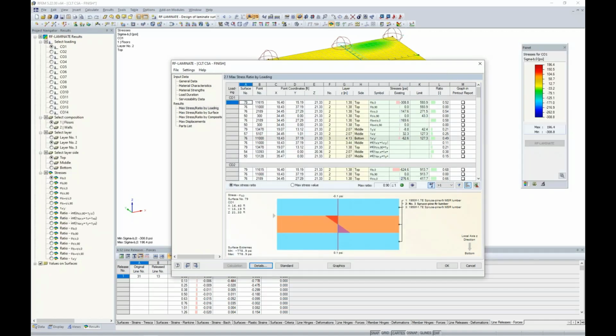So once you've applied the average regions, come in here, check on this checkbox. You can run your calculation again, and now we take a look at our max design ratios, and we see a max check now of 0.9. So that was significantly reduced from 1.81 clear down to 0.9 just by applying average regions and those FE mesh refinements rather than increasing the thickness of our panels or decreasing loads. So that is how you essentially can deal with singularities with CLT design.